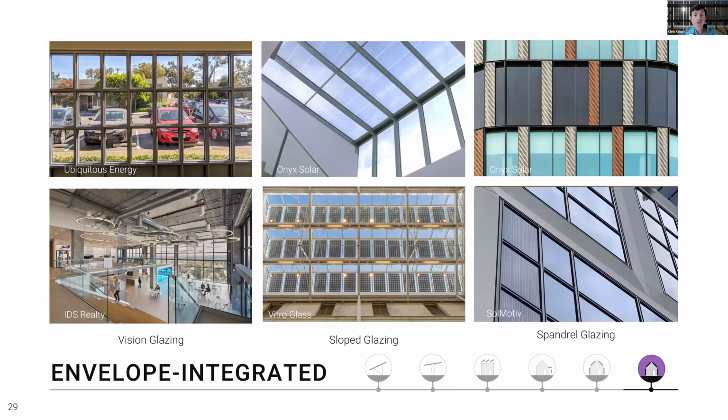Slope glazing offers the highest energy generating potential of the category and presents an opportunity to filter light in innovative ways. Crystalline technologies can be utilized similar to a frit pattern on glass, and thin film technologies can tune the visible light transmittance of glass by altering the thickness of their coating. Generally speaking, the more opaque a coating, the higher the efficiency.